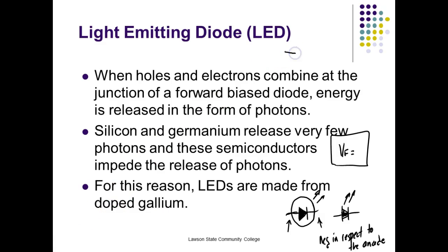One thing we can do is come over here and put a standard diode in series with it, and then put our LED right here, and then we'll put a resistor. So this right here would be the LED. This might be a 1N4001, which has a breakover around 50 volts. This guy here would be about 0.7, and this guy right here would be about 2 volts. So you're dealing with almost 3 volts drop.